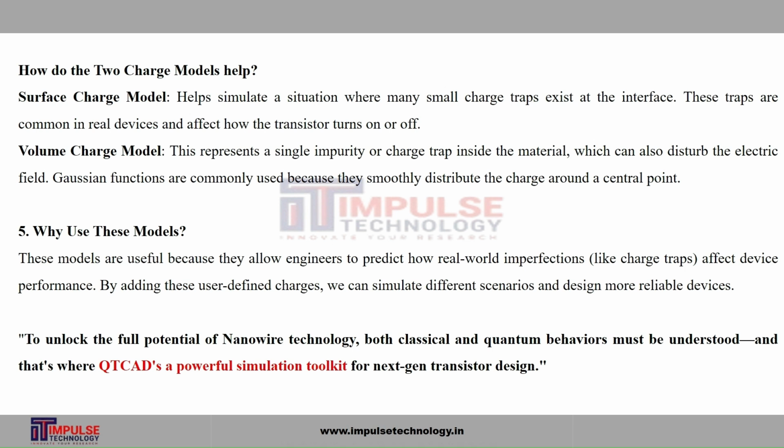This model helps simulate situations where many small charge traps exist at the interface between the semiconductor and the oxide layer. These traps are common in real devices and can affect how the transistor turns on or off. By adding a constant negative charge on the surface, we can simulate these traps and understand their impact on device behavior. This is essential for designing more reliable and efficient devices.